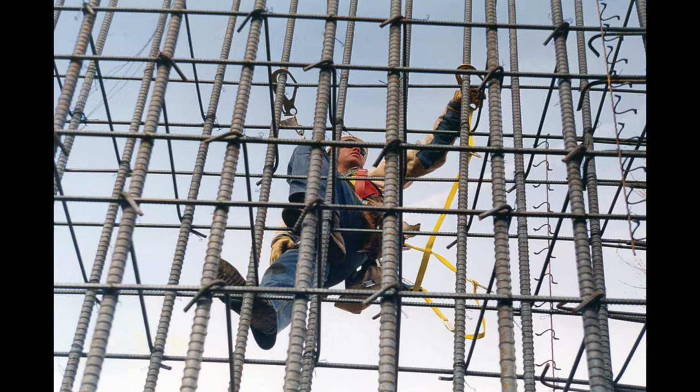Erecting precast concrete. We assume that it is feasible and will not create a greater hazard to implement at least one of the conventional fall protection systems for our precast concrete erection work. When our employees are erecting precast concrete members 6 feet or more above a lower level, they must be protected from falling by, number 1, guardrails or personal fall arrest systems.